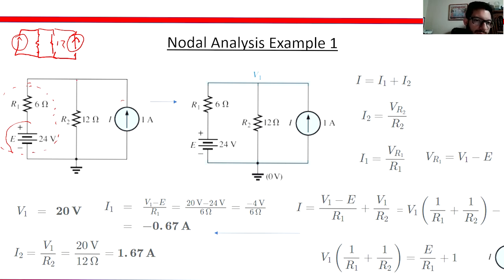You choose your maximum voltage node, which will be right here, this node, which keep in mind that even though that's your node, all this branch has the same potential, V1, even though you chose that node. And all this branch has the same potential, which is common, that was 0. All right, so that's the first step, choose your nodes. So we have two independent voltage nodes. Right here, there's V1 and then your ground. You always have to find those.